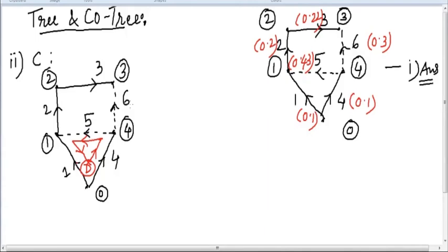Okay. Now let us make a different color for this. So you all know how to make the loop. The loop will contain only one link and the rest all branches. Otherwise you will get confused whether this loop is to be taken or not. If you take this loop, it will be wrong, because in this loop there are two links. So at a time there should be only one link which you have closed to form the loop. So that's why the loop will be in this way. It will start from here, then move to here, then here, then go downwards in this way, then upwards in this way, and finally return back to the position.